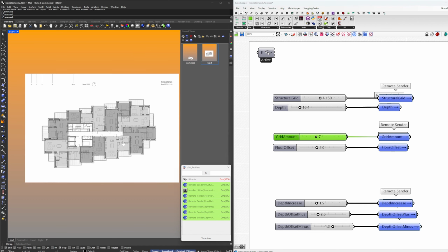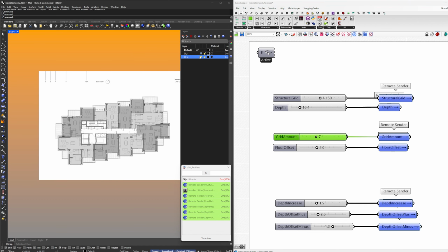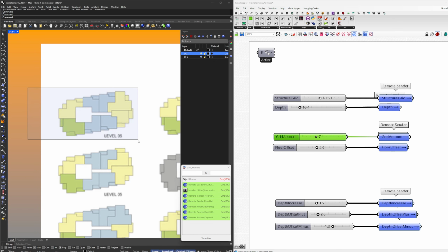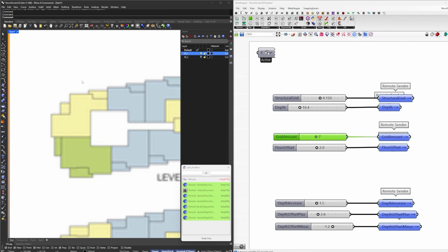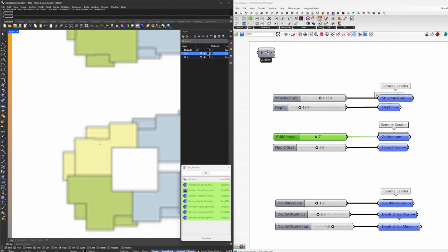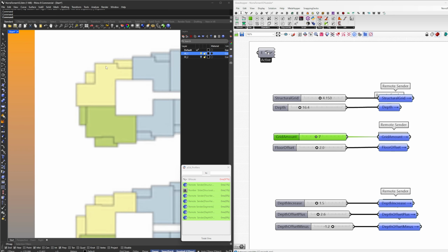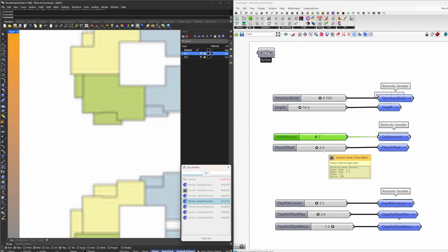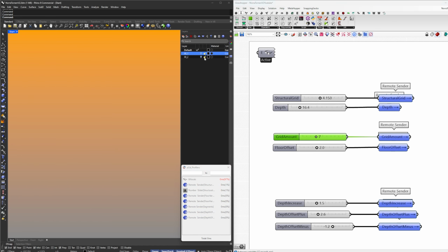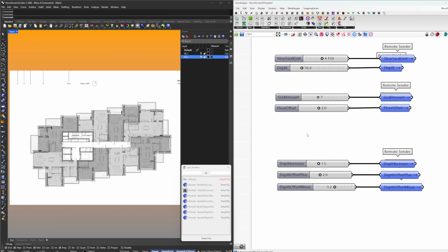There's a floor offset. That is because we have our 2 starting documents, also this one. The pattern of the floor segments are alternating. So here it starts in a Y direction, and then it goes a bit back and then goes to the front again. The opposite is for the other floor. So it starts back, then front, then back. So the difference between this one and this one is an offset of 2 meters. Okay, let's get back to our main floor. That is this guy.